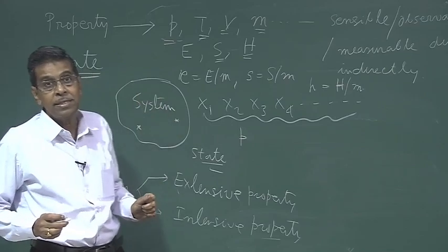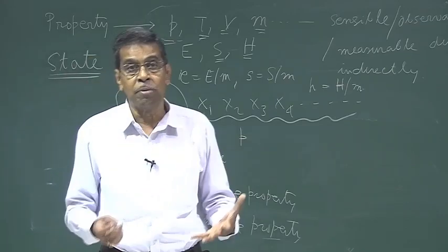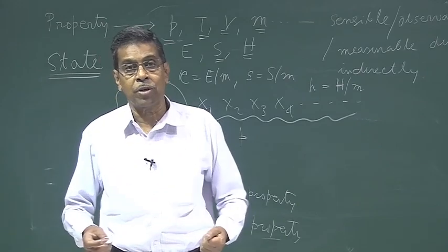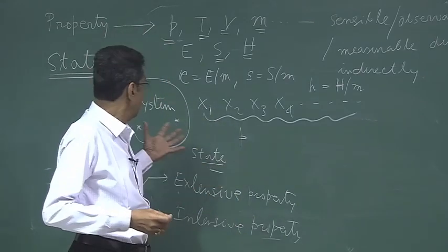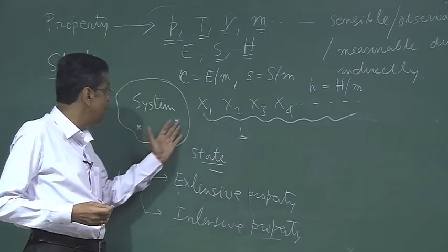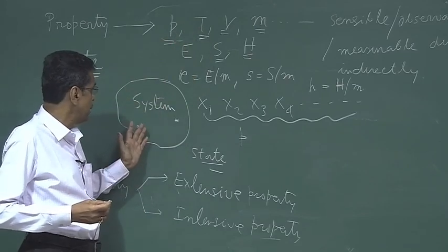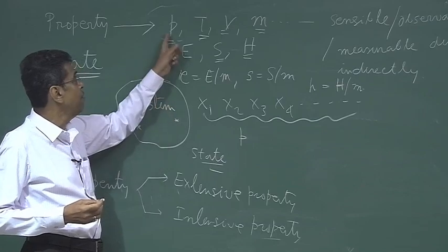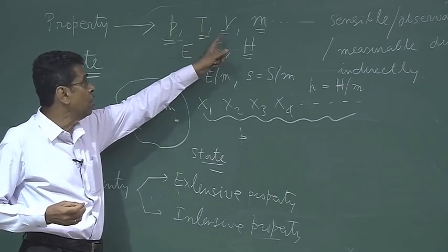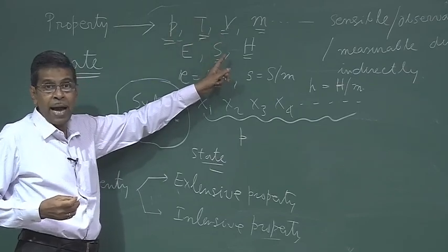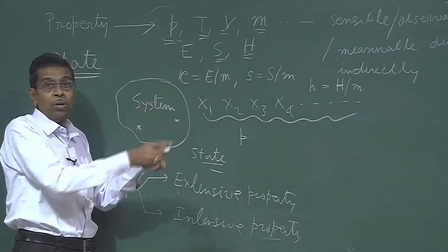This is the state of thermodynamic equilibrium of the system, which will be discussed again afterward, where internally there will be no variation in the intensive properties like pressure and temperature. They will be uniform, so that the system can be described by single values of these intensive properties along with the extensive properties, and at the same time they do not vary with time.